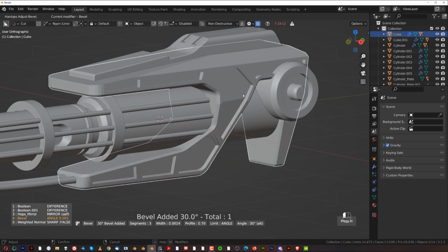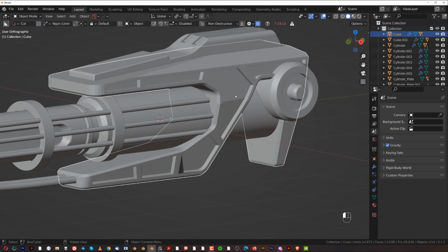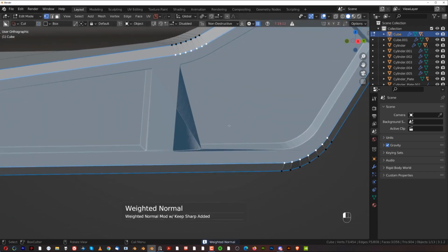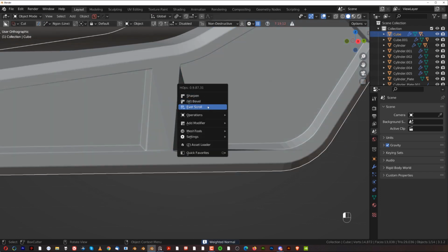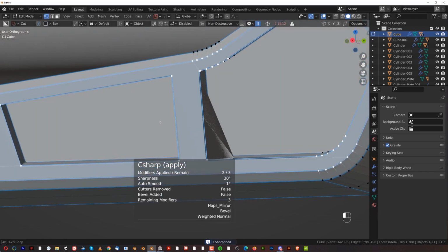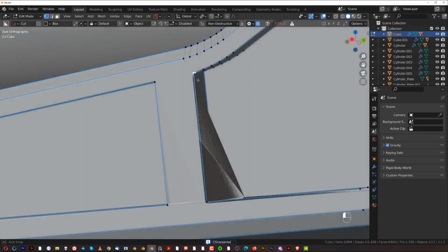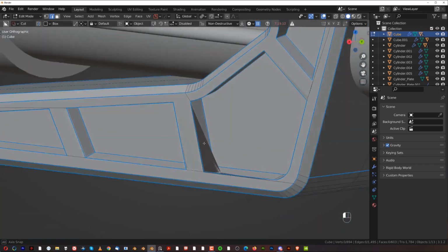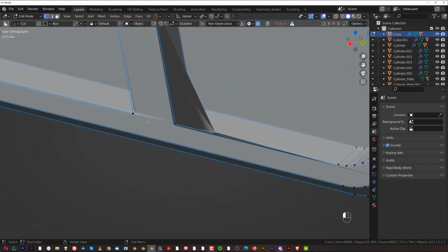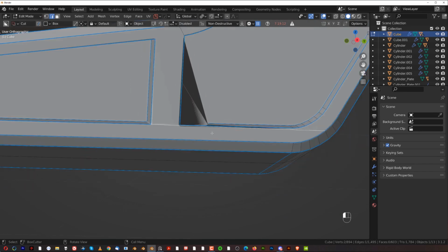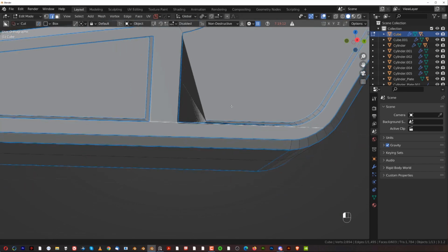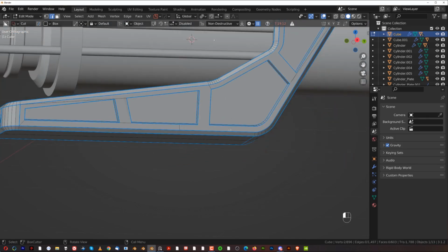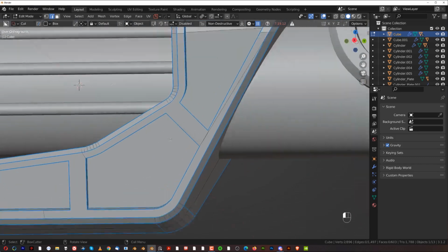Now you're gonna have some problems with bevel for sure. We're gonna have some overlappings and stuff, but we can easily fix it. So if I'm going to sharpen this, then we can start cleaning problems. Like here, for example, there is an issue. This edge is way too close, so dissolve it. Here too, this edge is causing problems, this long edge. So what we need to do is simply connect it in here and then remove this one, okay, and solved. And that's how you solve all your problems.